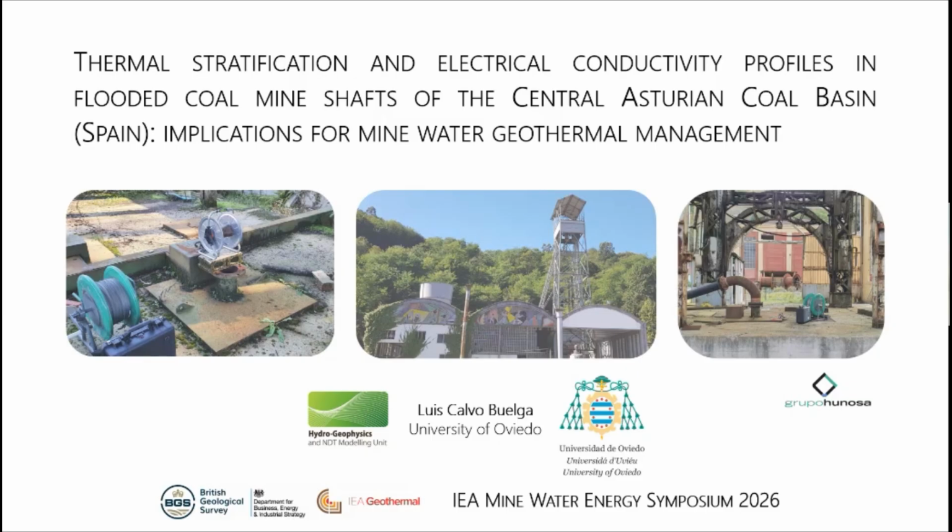To support this, an important part of my research involves field data acquisition in flooded mine shafts across the Central Asturian Coal Basin. We perform vertical profiling along the shafts, reaching depths of up to 400 meters, where we measure pressure, temperature, and electrical conductivity. Pressure data allow us to determine depth and locate the water level, while temperature and conductivity profiles help us understand the thermal and hydrogeological structure of the system.